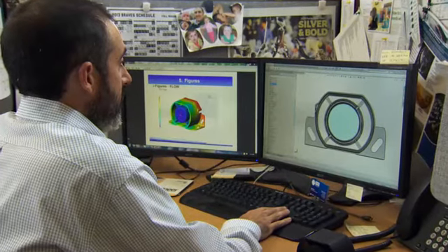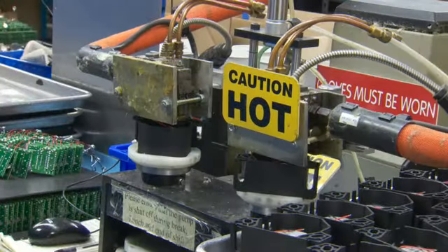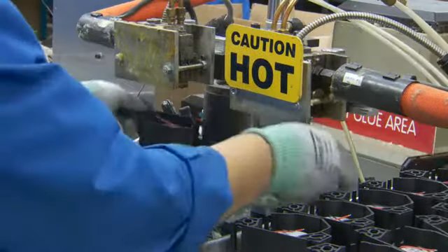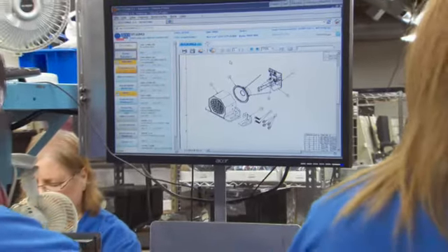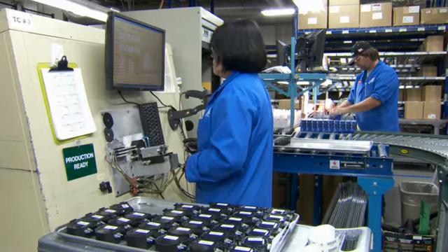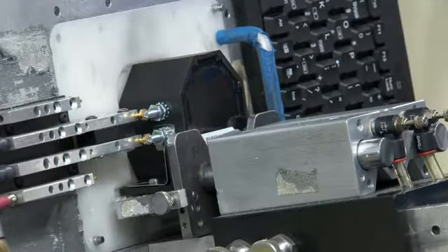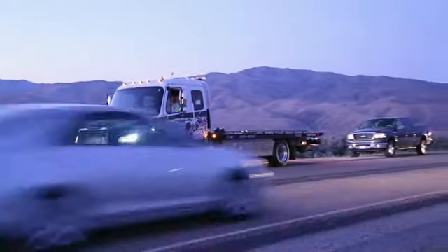So the design idea was to take that same shape, but make it into a single molded part of glass-filled nylon. Well, we were able to validate by making a part out of glass-filled nylon, adjusting the thickness to find out, well, how thick does this have to be strong enough? Where can we add fillets so that we don't have any stress points? What kind of force is this alarm going to see in regular use?